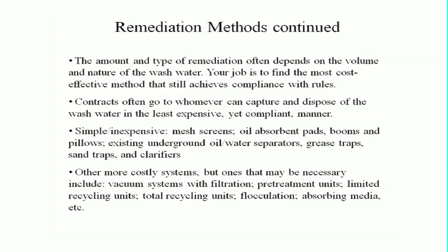Remediation methods. The amount and type of remediation often depends on volume and nature of the wastewater. Your job is to find the most cost-effective method and still achieve compliance with the rules. Contracts often go to whomever can capture and dispose of the wastewater in the least costly yet compliant manner. Simple and inexpensive options are mesh screens, oil absorbent pads, booms, and pillows. Then there are existing underground oil water separators, grease traps, sand traps, and clarifiers.